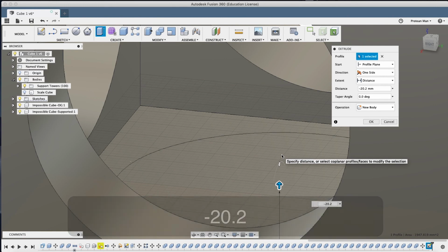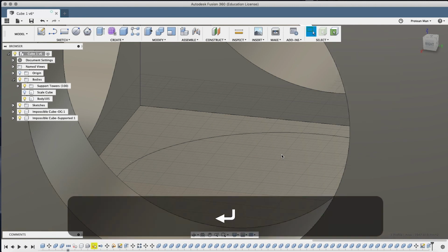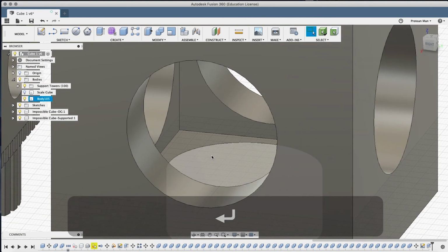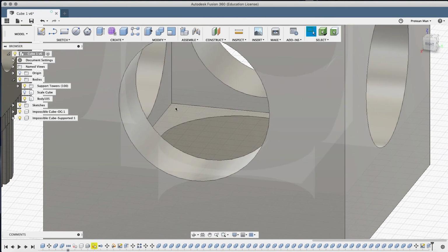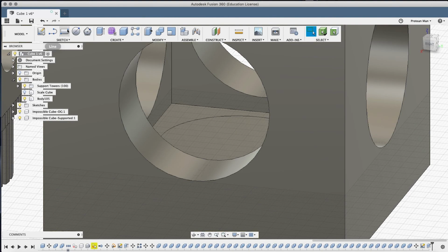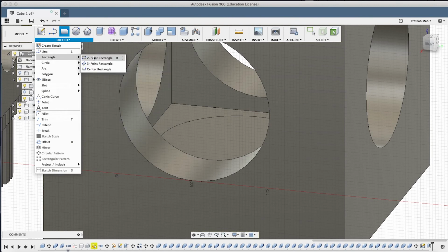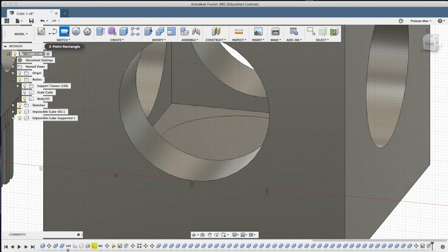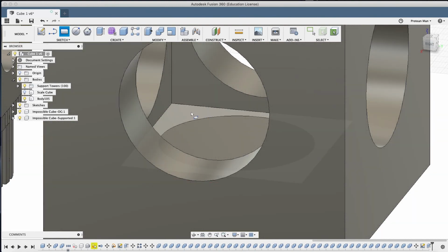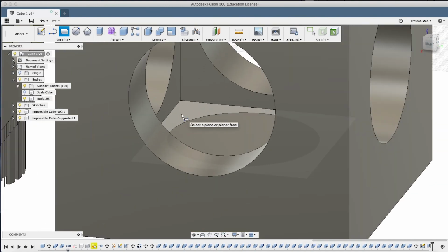And that's good. Okay. So here we go. Here's the next fun part. We're going to create a new rectangle. We're going to go sketch, rectangle, 2-point rectangle, or it's already in your top menu if you followed all the instructions from previous videos. Click the middle of the large cube, the bottom layer, the one where a new cylinder is attached to, or sort of around.